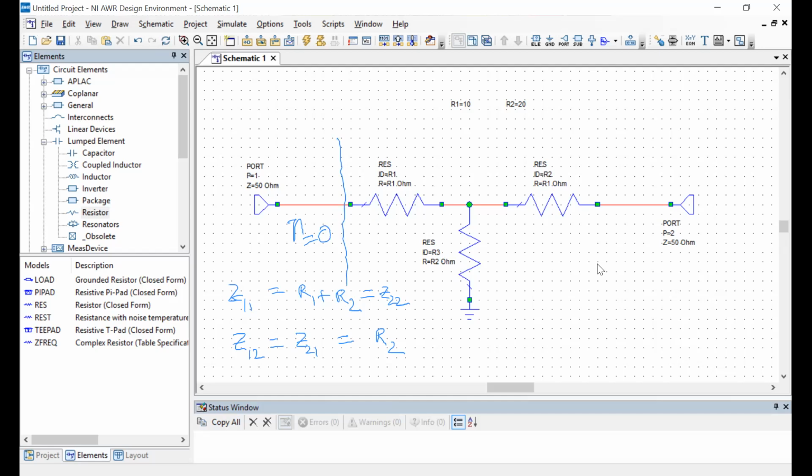Yes. Right? That's what matched means, that you cannot have any reflection here. Similarly, at this plane, this reflection coefficient has to be 0. Now, because this circuit is completely symmetric, if you ensure one, the other one is by definition going to be fine. And then there has to be some transmission coefficient, which we can call T, which has a certain value, which basically is the attenuation factor.